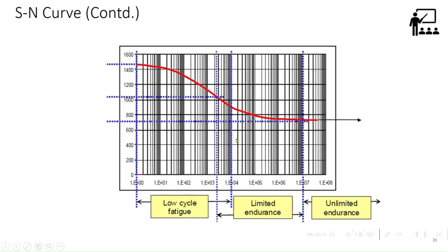And anyway, composite is known to have good resistance to fatigue. So nobody bothers about fatigue in tension or such. It is only a concern when it is subjected to compressive load with impact loading, which may induce some delamination, and so on and so forth.